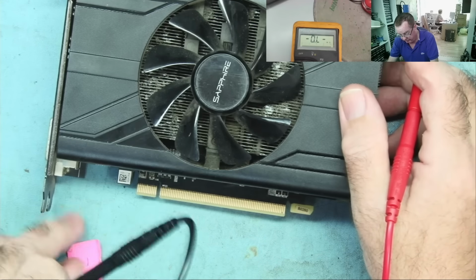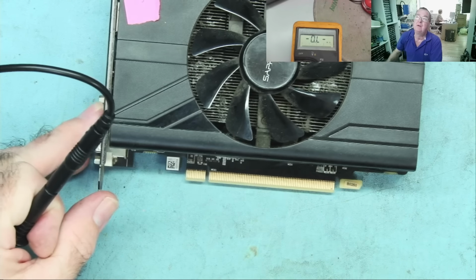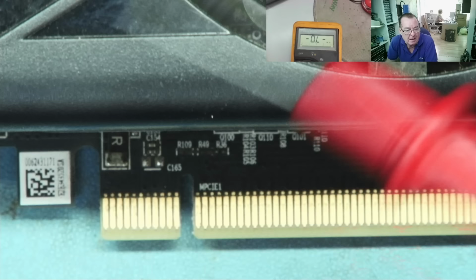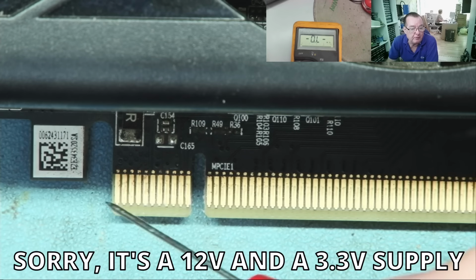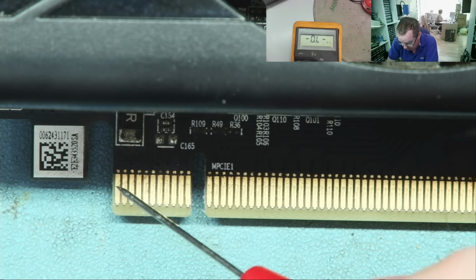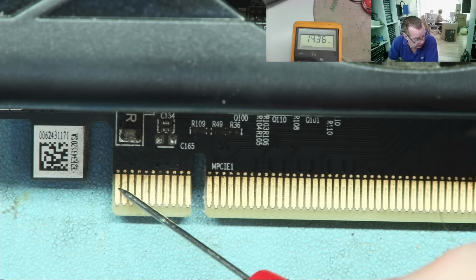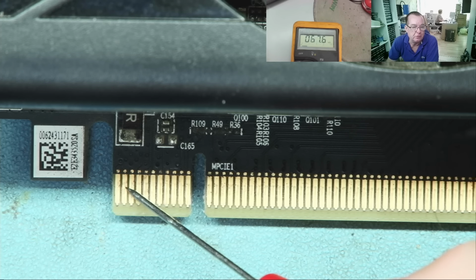Okay, the other input pins are over here. So here we have a 12 volt and a 5 volt. 12 volts is on the first three fingers here, so you'd expect them all to read the same. 1.2k, just dropping slightly. No, now it's gone to 8k. That's my auto ranging meter that's causing it to do that.